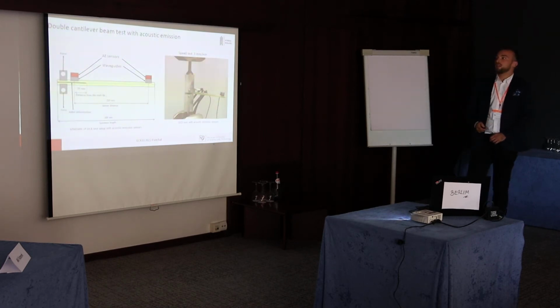Our first experiment is a double cantilever beam test with acoustic emission system. We put the acoustic emission sensor on the end of the bar.